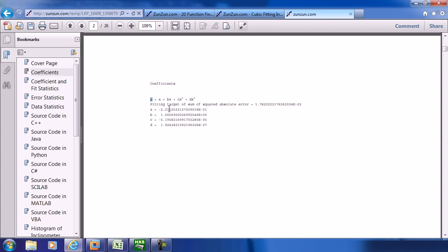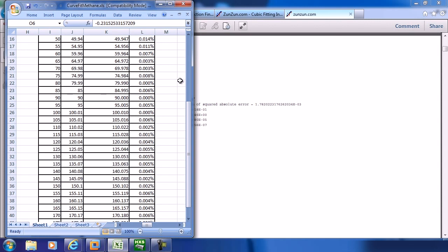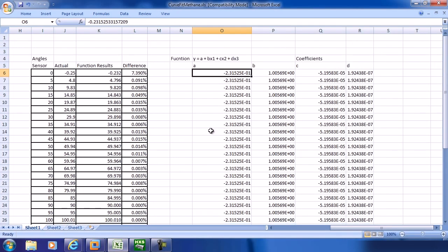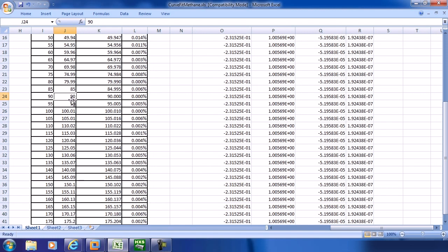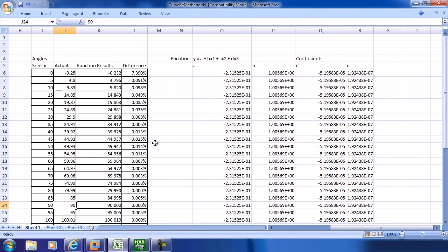Once we have all this information, I went ahead and dropped it over to a spreadsheet here, so we can once again see here's the angle coming from the inclinometer. There's the actual angle of the pipe, so we can see that gravity is playing a role on it. At the other end of the spectrum at 180 degrees, we can see gravity sagging there in the middle. Not too much of a gravimetric effect because it's being nicely supported right in the middle up on top, so there's no angular displacement.